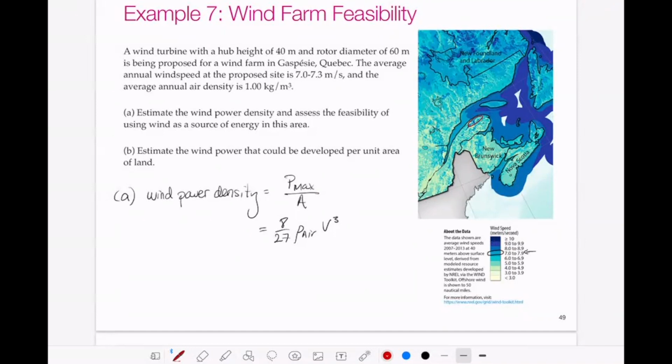If we always calculate our wind power density this way and compare it to our tables, and it's not class 3 or greater, then it's not really worth doing because achieving that kind of power is not overly reasonable. So this is convention. You could use average, but if we look for the max and we always follow the same rule, and all of the tables are based on this type of analysis where we're looking for that max power, then it essentially would achieve the same thing.